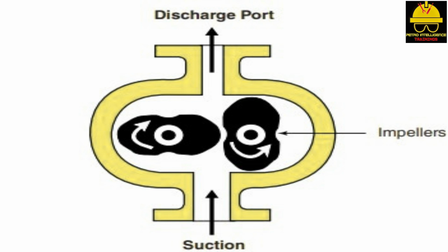The drive shaft forces the idler shaft to turn through the gears. The gears and bearings are located on the outside of the compressor. Compressed gases are released to the discharge line. The internal lobes on a rotary lobe compressor are designed not to touch. A few thousandths of an inch clearance exists between the casing and lobes.